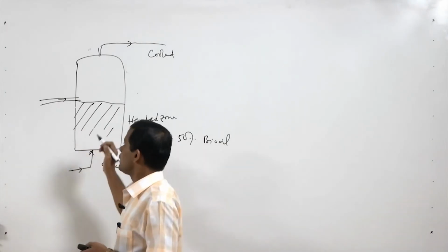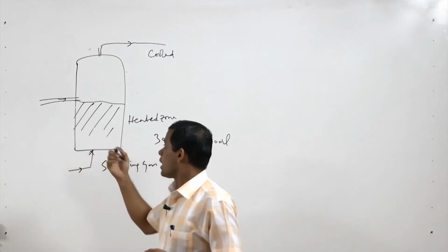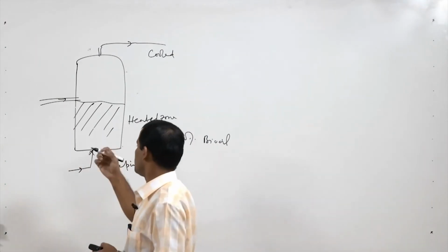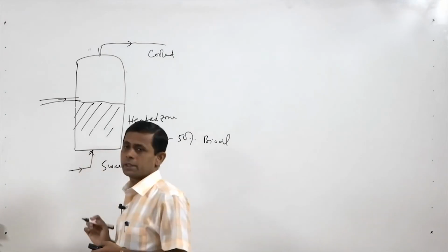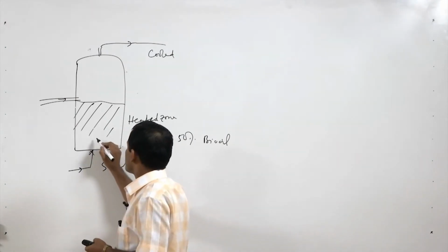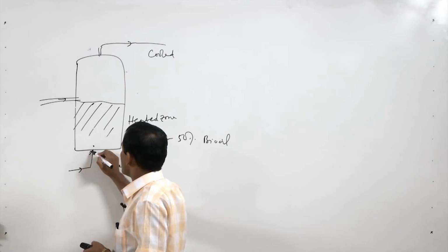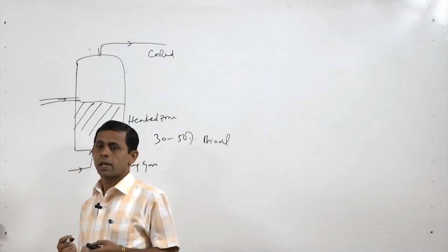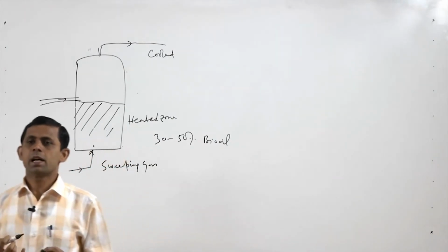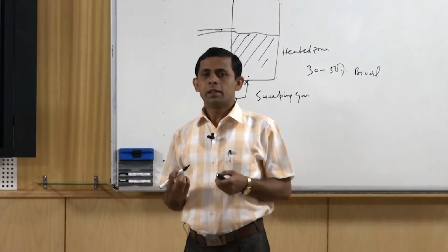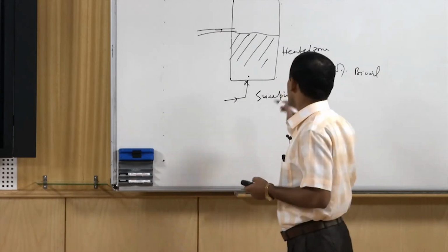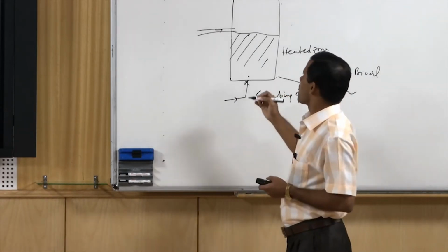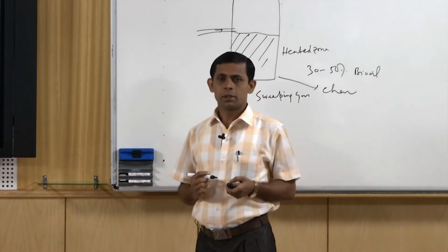Sand is used there so that it has a high heat transfer coefficient, and so the rate of heat transfer is more in those reactors, but here the rate of heat transfer is less, and basically gas to solid heat transfer takes place. There is no solid to solid heat transfer. That is why the time requirement is higher, the residence time is higher. As a result, the char production is also high here. More char is produced and less bio oil is produced.